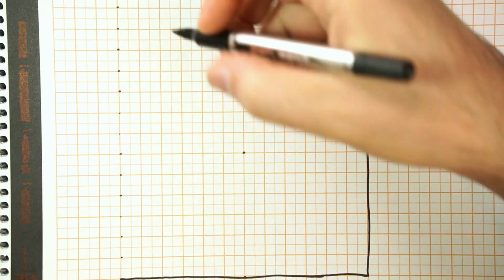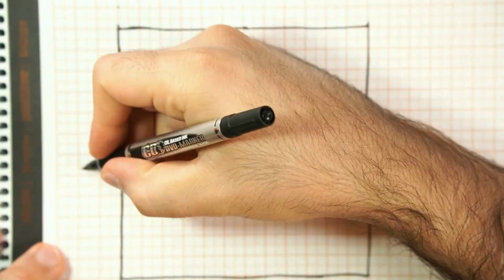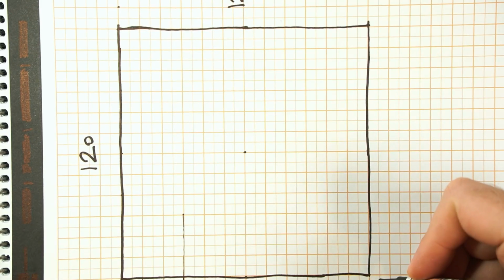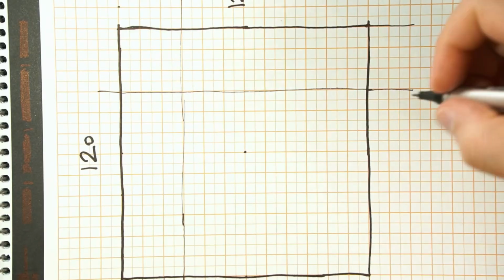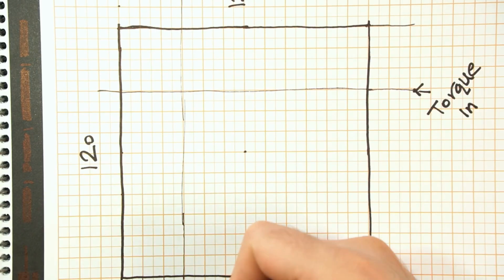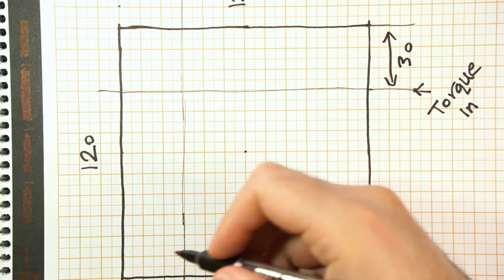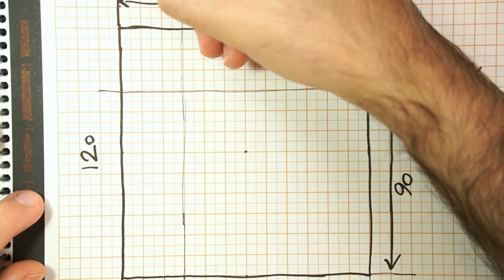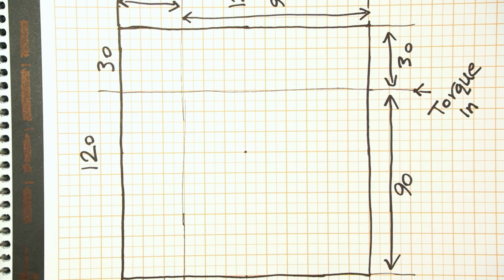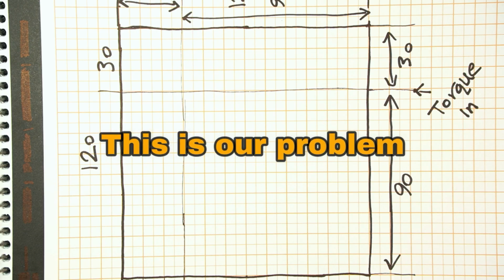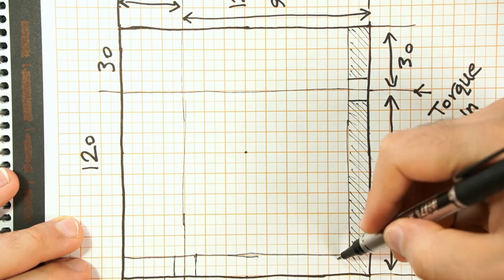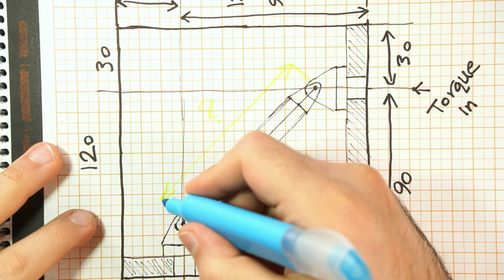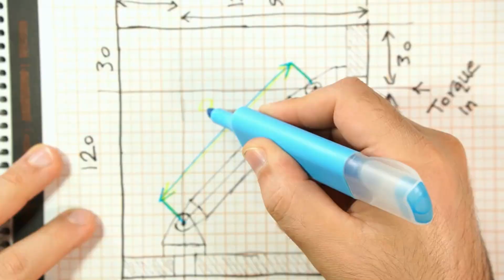I start our example lesson by sketching on paper, just as I mentioned earlier. First, I draw the problem, a 90-degree torque redirection device. I sketch the boundaries of the available space for the device and mark the positions of the input and output shafts along with their given dimensions. Then I complete the sketch with my solution, including the dimensions and positions to be used in the CAD process.